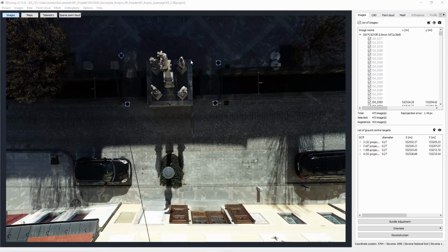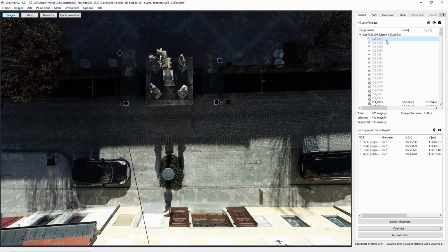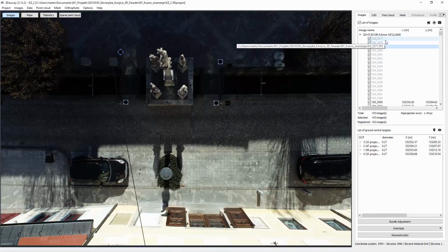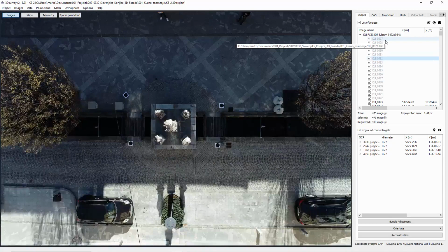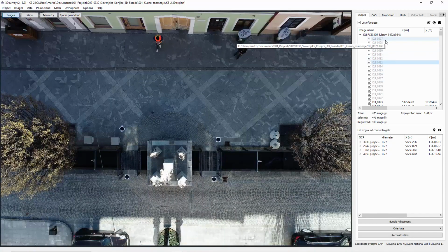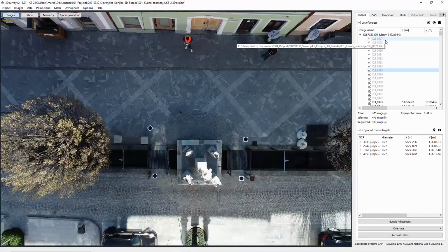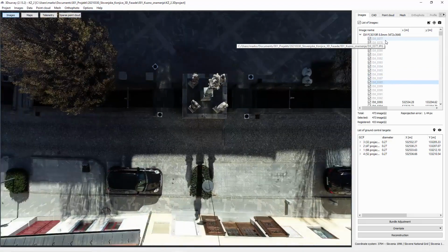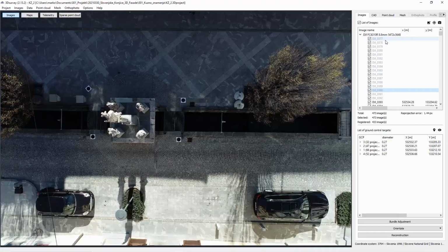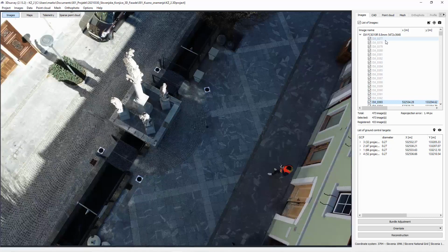And before we look at how we fly, I will just go image per image. Then you can get a quite good feeling for how I was actually triggering images. So first I decided on nadir camera view, the first 10 images, for example.